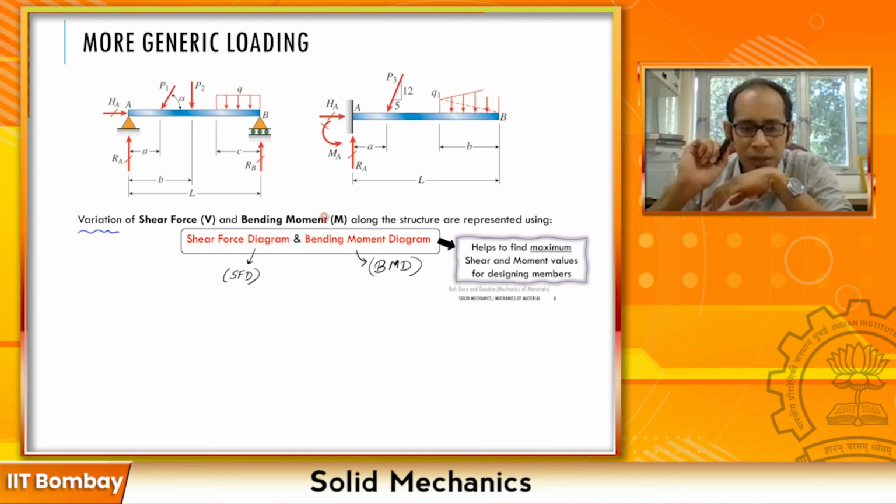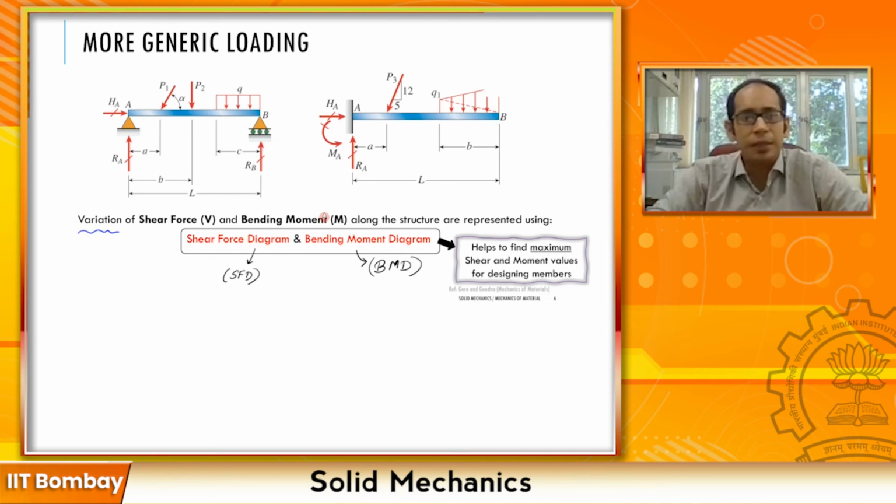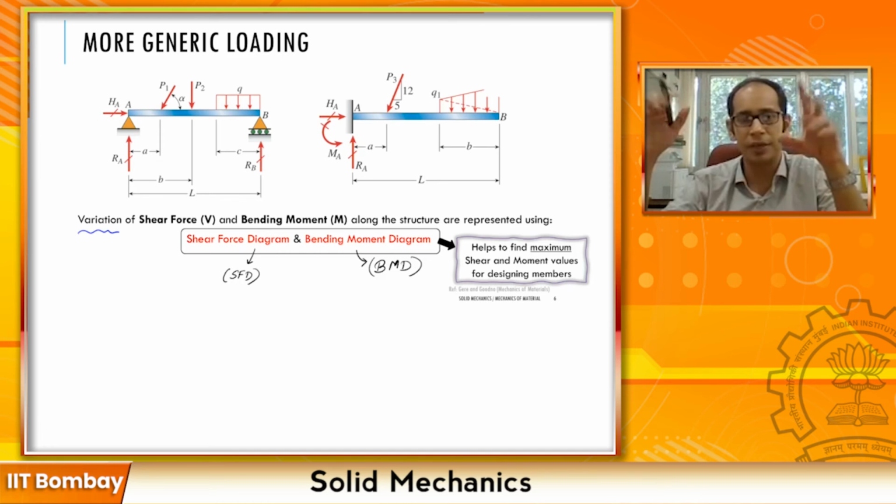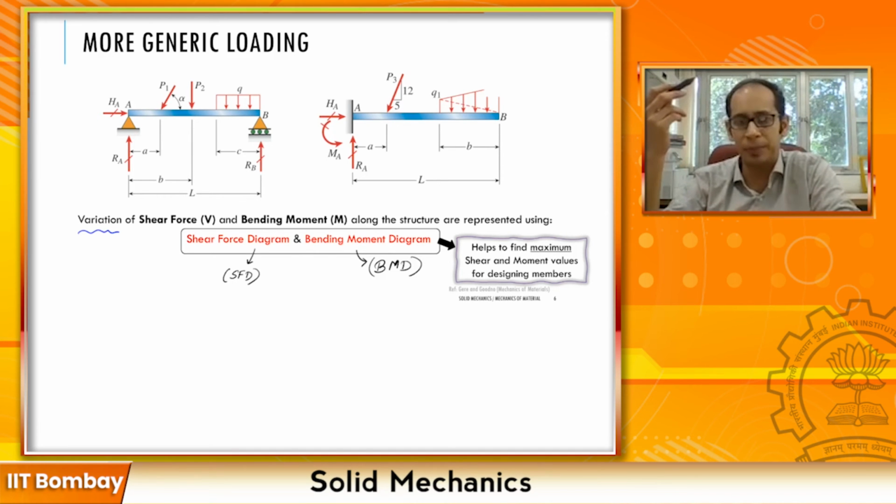Well, the critical point that you have to remember is that you design structures such that they don't fail at the points of criticality, at the points within your structure, the room where you're sitting in, the beams and the columns and the slab, right? The points along the beams are subjected to all the different kinds of loading, columns are subject to different kinds of loading. The points within these beams and the columns and the slabs, if you draw the shear force diagram along the length of the beam or the bending moment diagram along the length of the beam, you will see that there are points where these values peak, these values become maximum. So if you had to keep on increasing the load, these points become prone to failure.